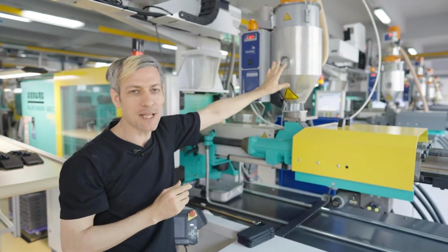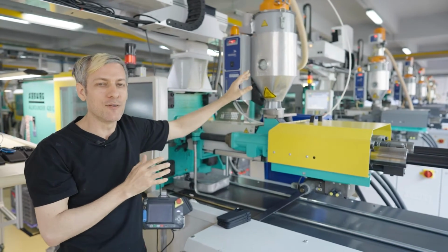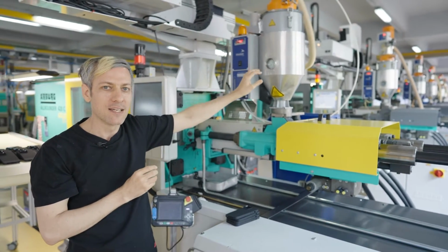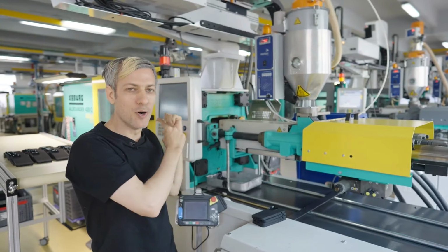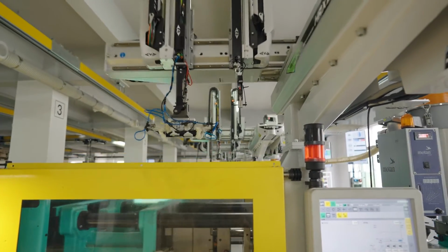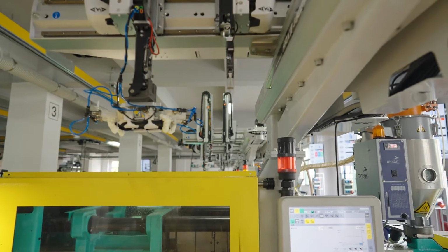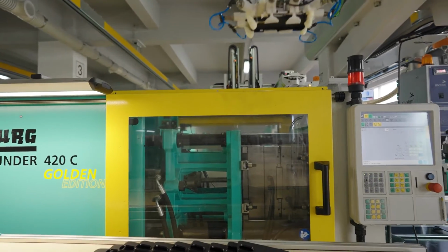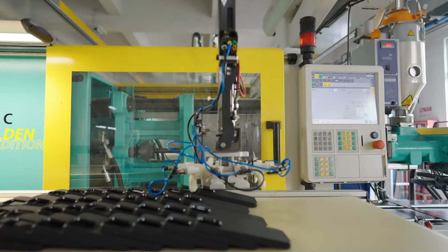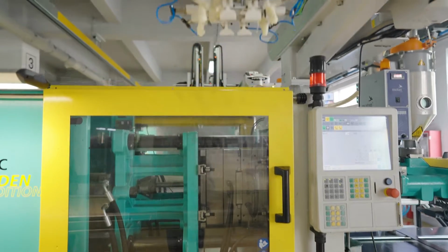So it dries the plastic out. And this is important to remove all the moisture from the plastic because it creates instability in the mold process. Potentially the water can boil out, but it also causes issues with heat because as the water boils, it cools the parts down. So that's why they have to remove as much moisture as possible from the plastic.